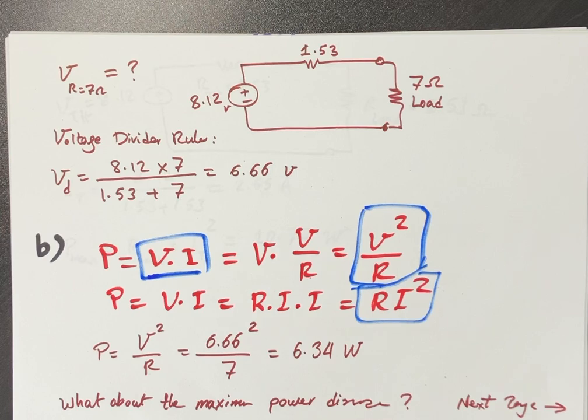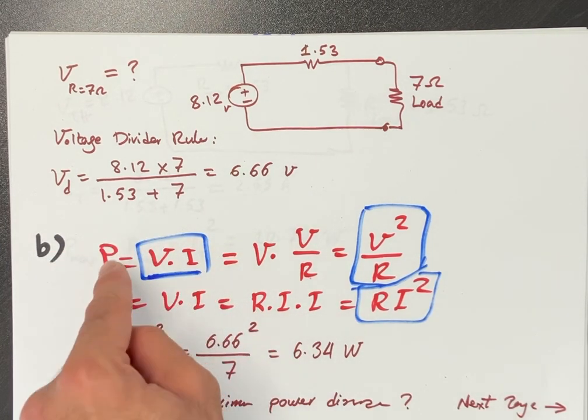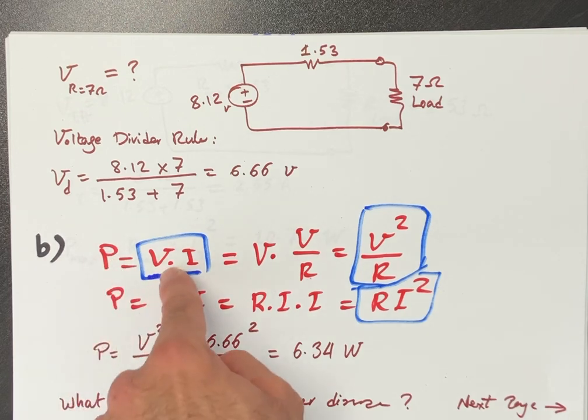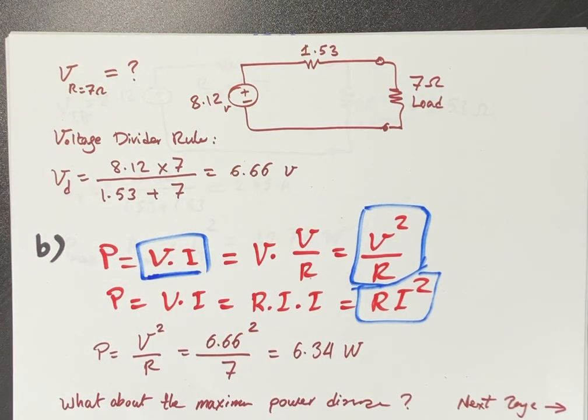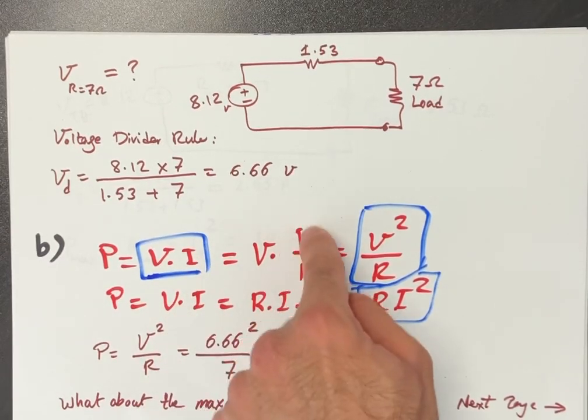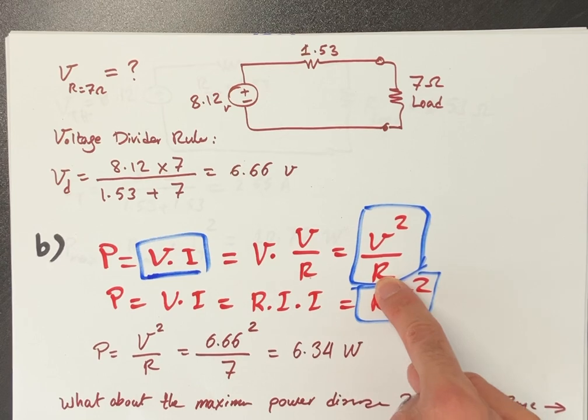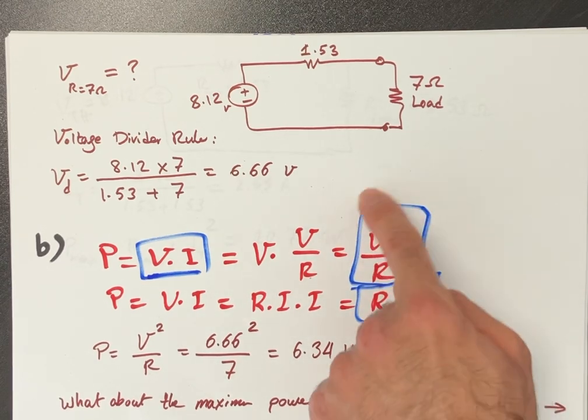Part B is about power. These are the general formulations you need for power. I should say the only one you need to know is the definition of power in electrical systems. Electrical power equals multiplication of voltage and current. Then, sometimes you may not have current. So in that case, this current can be replaced by V over R based on Ohm's law. And this gives you V squared over R. So if you remember this one, you can quickly apply this one.